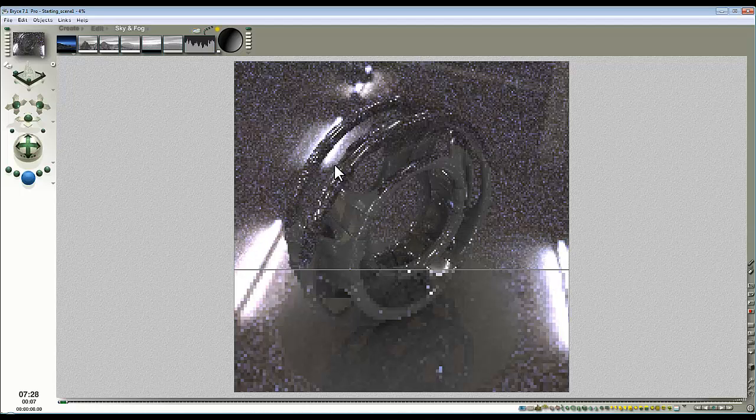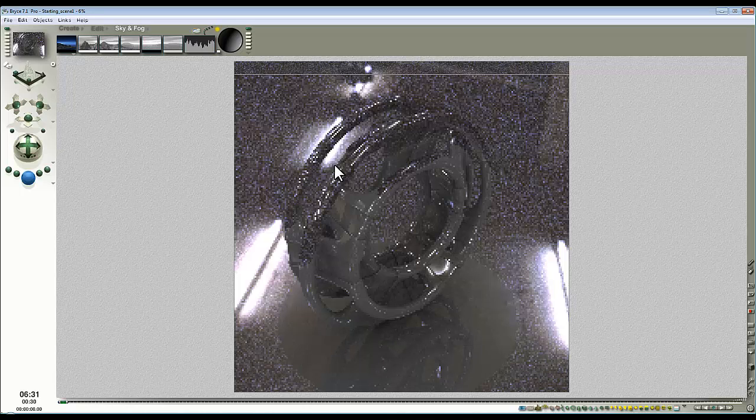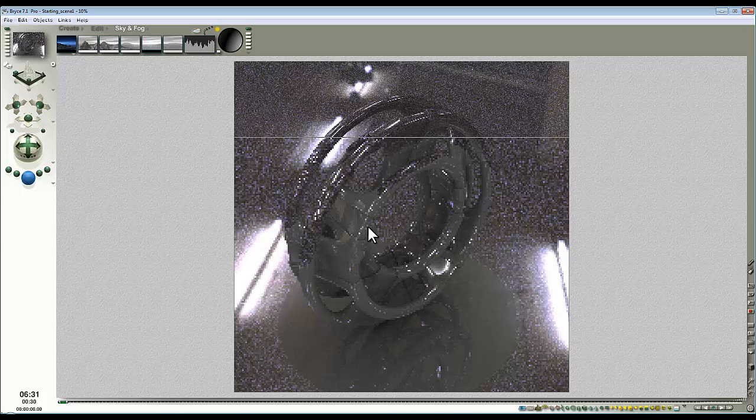And because the high dynamic range image has not been tone mapped, the reflections are just suppressing everything essentially except the brightest elements in the scene, because it's only 15 reflection in the material option, so we're seeing the fluorescent lights and perhaps a bit of overspill around those. So this is an interesting effect, I think, but perhaps not a very useful one.